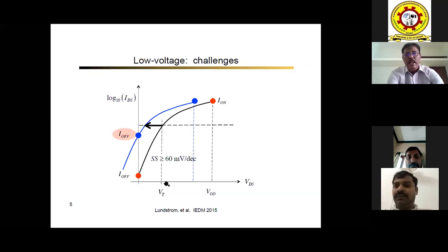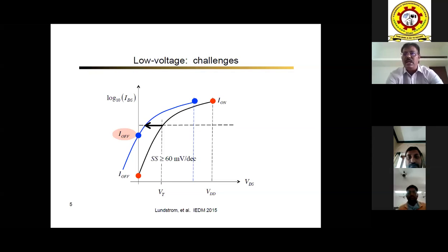The device runs in normal mode after the threshold voltage, meaning your conventional FET turns on beyond the threshold voltage, because the threshold voltage is where it develops your inversion layer and carriers start moving from source to drain. Sometimes researchers are interested even below VT.